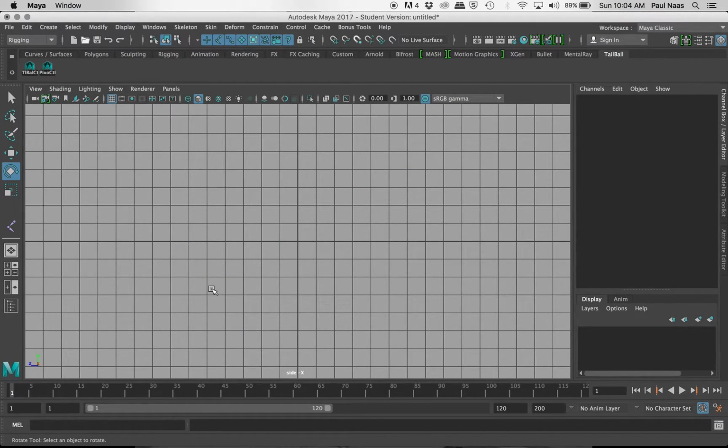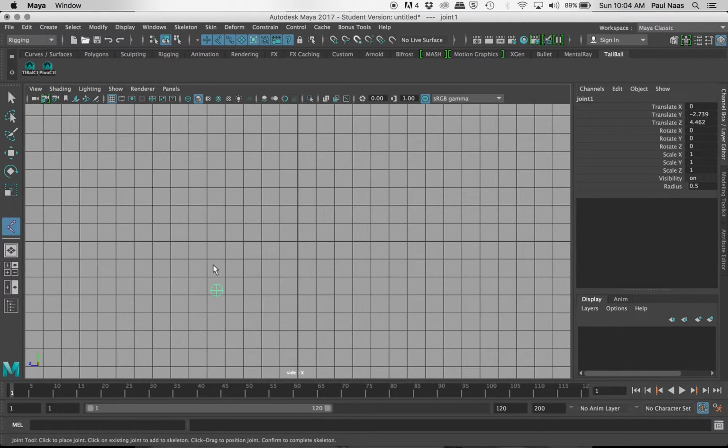Another thing to be aware of when it comes to creating joints: if you watch this joint here, when I create this joint here, watch what happens to that little plus sign. See how it flips and it's now oriented down the bone length? See, that one did it too. This one will do it. See how it flipped there?